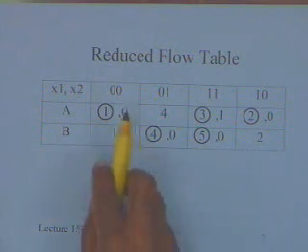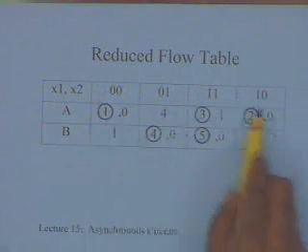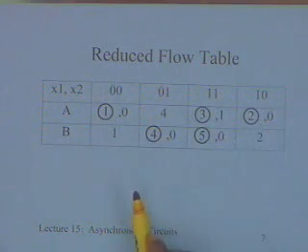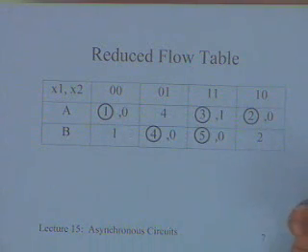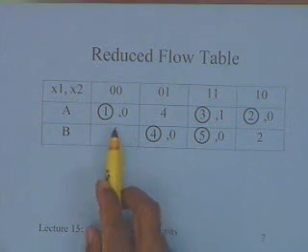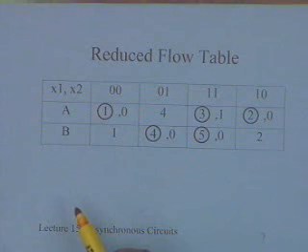What is the implication when I go from 0 0 to let us say 1 0, when I make this transition from stable state 1 to stable state 2? In this mode I will not have any transients, I will directly go there. But when I go from 0 0 to 0 1, I am going through a transient state. So I have to now define what is going to be my output at this transient state.